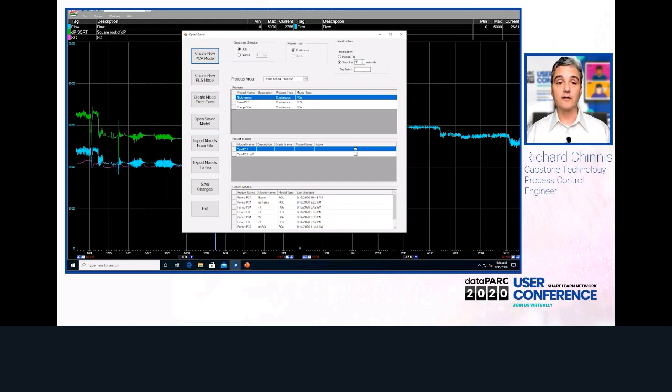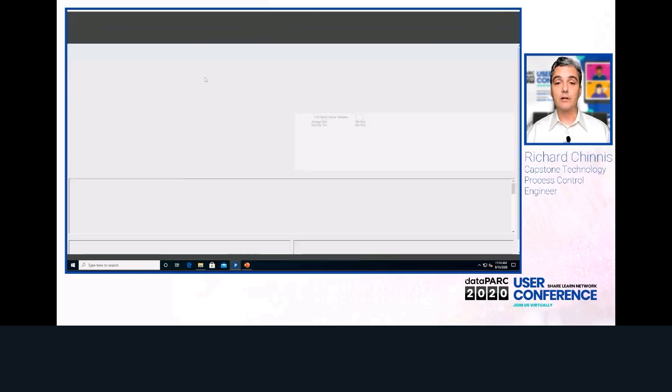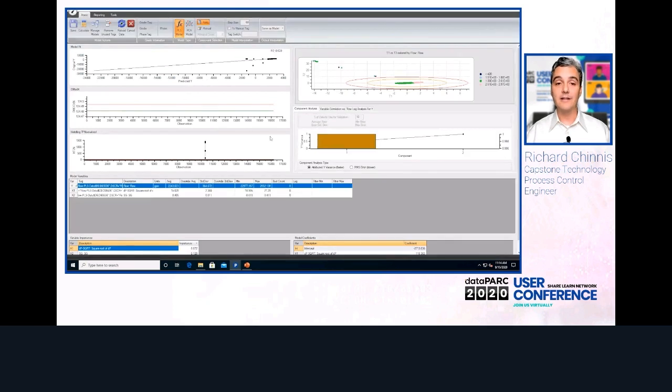That's sufficient. Sometimes for flow, you need a much faster step size, but in such a case, as you can see, I'm using 11 days. You wouldn't use 11 days of data if you needed to tightly model a very fast responding flow. So I'm going to leave all of these settings the same, and I'm going to create a PLS model. And when you click create, it's using all of the data that's in that trend that you saw, that entire 11-day time period.